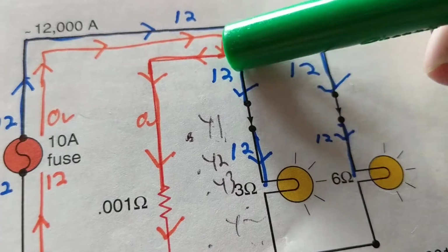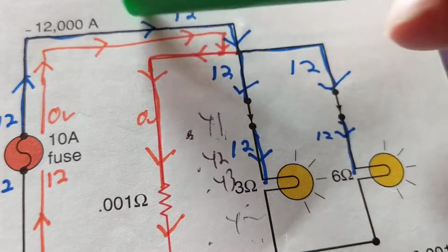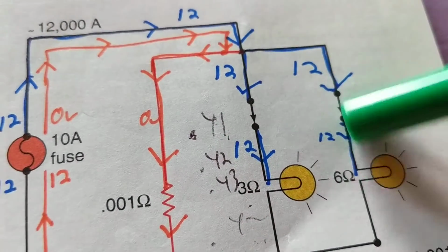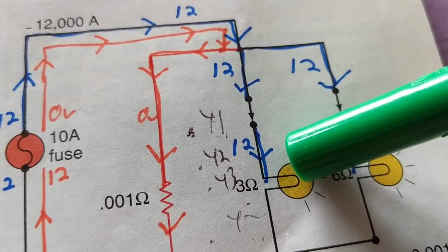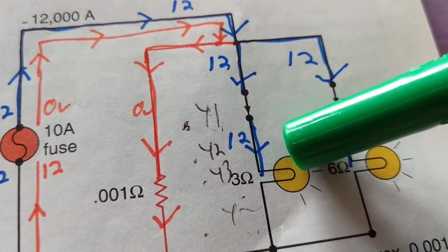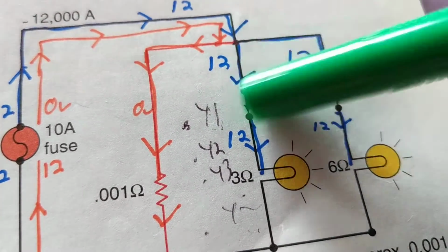How much am I going to measure here? Since we have no connection going back to the battery, guess what? 0 volts here and 0 volts across each. Both will be extinguished, not illuminated, not lit. When we see that, we know there's a common one causing both.